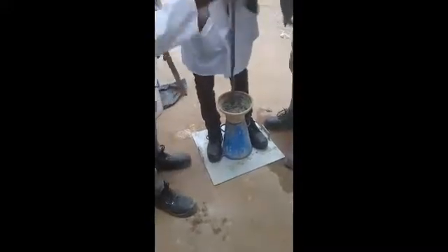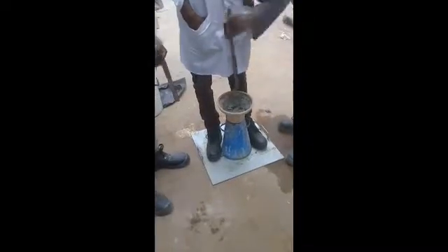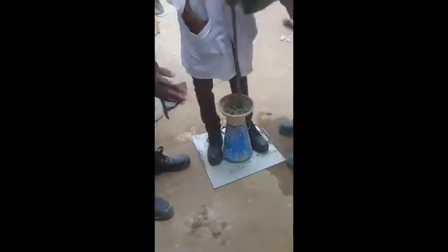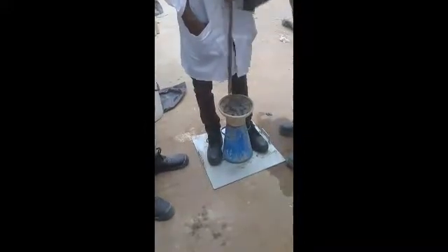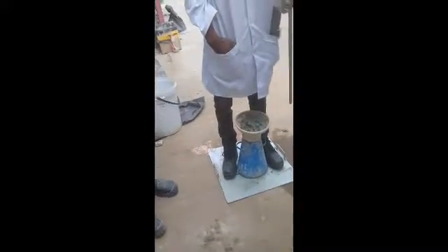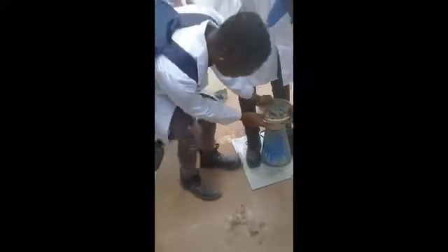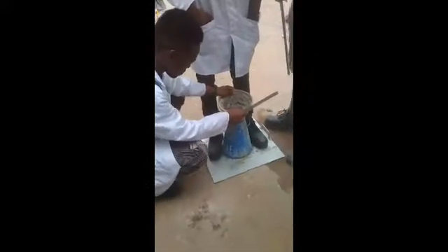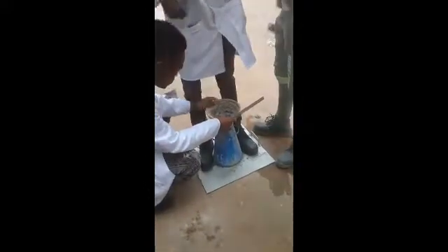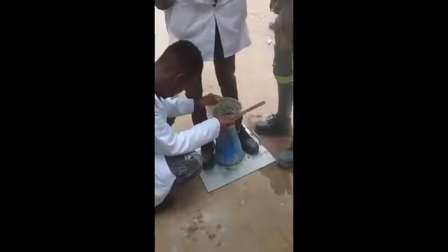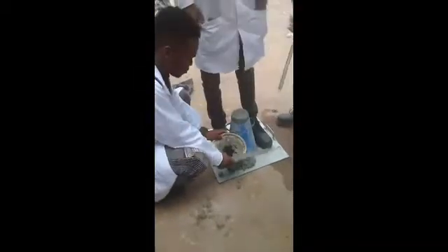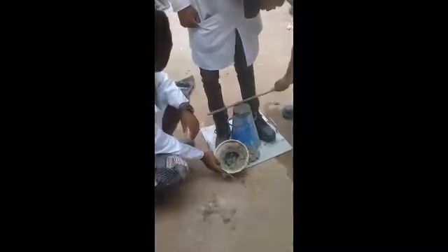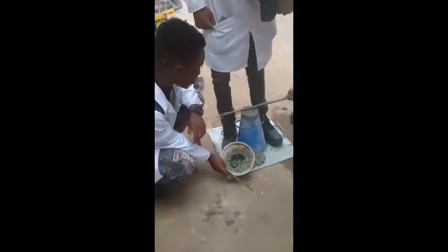The tamping was performed using a 600 mm long bullet nose metal rod with a diameter of 16 mm. And even though the tamping appears to be fast on the video, the layers were actually tamped slowly to make sure the counts were accurate. And as the cone was filled with concrete, the top of the cone was slid so that the excess concrete leaves the top of the cone, and then it was leveled using a rod.